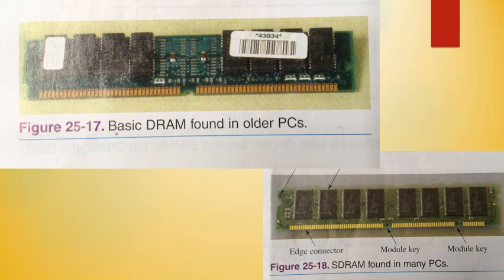The capacitors hold electrical charges in patterns matching the binary data patterns. While large capacitors can hold an electrical charge for a long period of time, the microscopic sized IC capacitors cannot. Because the capacitors lose their charge quite rapidly, they must be constantly recharged. The constant recharging is referred to as refreshing, and how often it occurs is called the refresh rate. Typically, the RAM needs to be refreshed thousands of times per second.